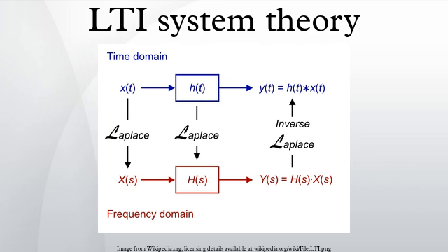Suppose the input is x[n]. The output of the system with impulse response h[n] is then the convolution, which is equivalent to the following by the commutative property of convolution. Where H(z) is dependent only on the parameter z. So the exponential is an eigenfunction of an LTI system because the system response is the same as the input times the constant H(z).